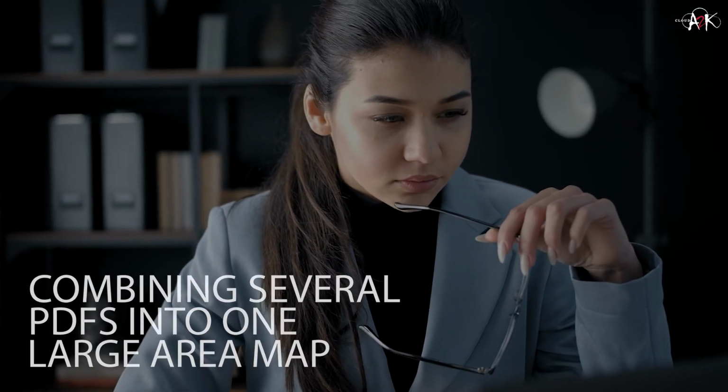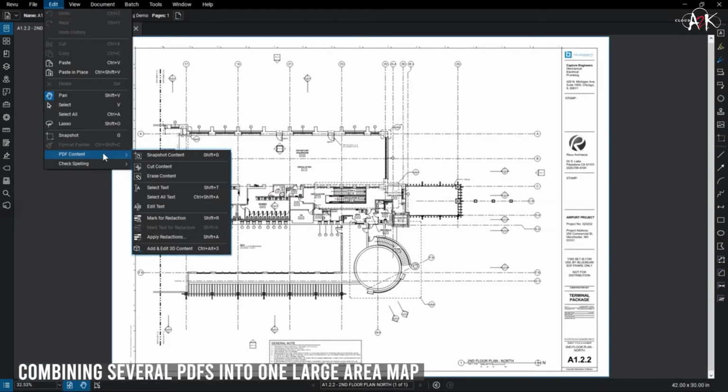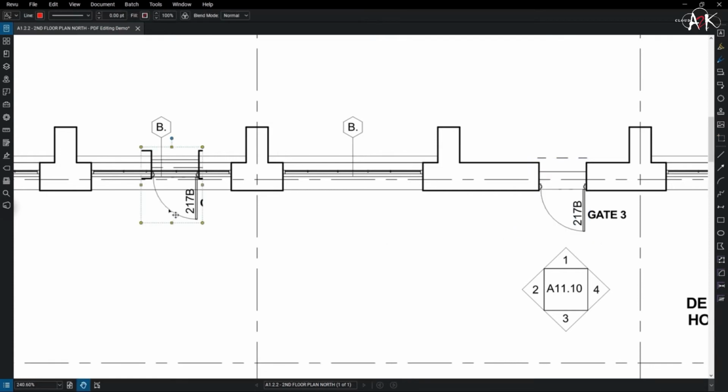Combining several PDFs into one large area map. If you start a new PDF with an oversized blank sheet, you can use the snapshot tool to collect portions of separate sheets, pasting them onto the new document. When using snapshot, the image comes in at the same scale it was taken from, so you can easily piece them all together like a puzzle. Grouping them once you have the puzzle together will avoid accidentally moving an object.